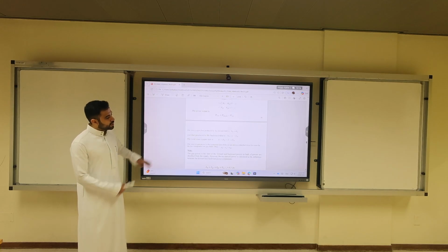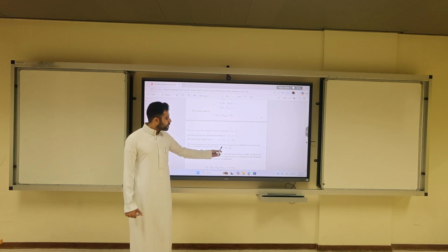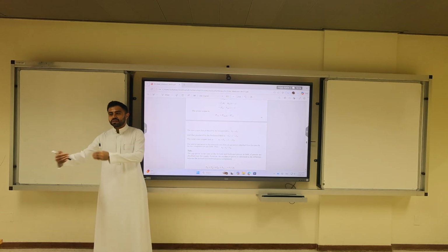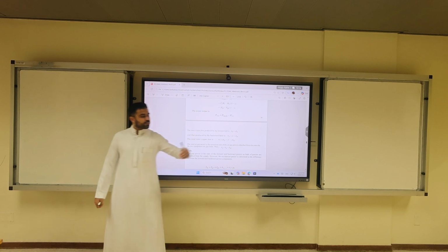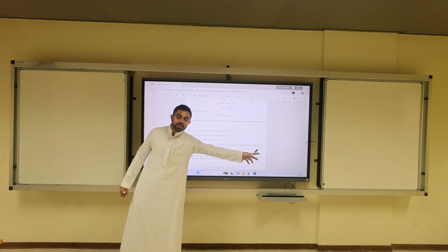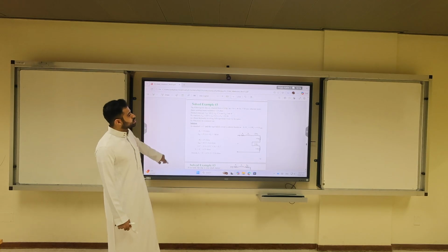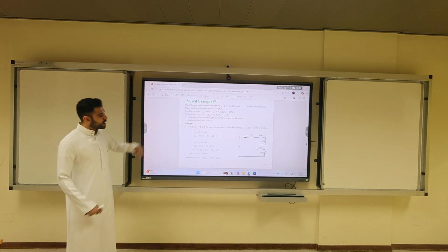The other equation, if you look at the air gap power, it's additive. So in terms of power consumption, I'm adding the forward and backward. In terms of the output torque, I'm subtracting the forward minus the backward. So let's do this example again one more time.